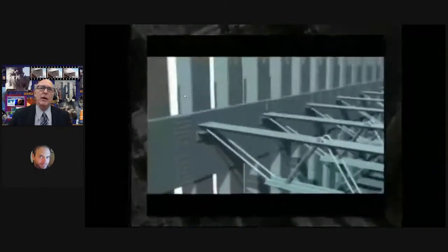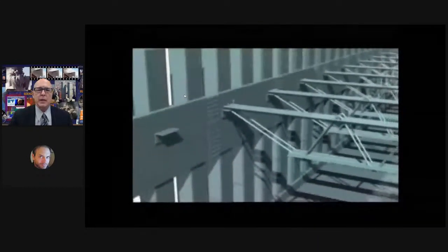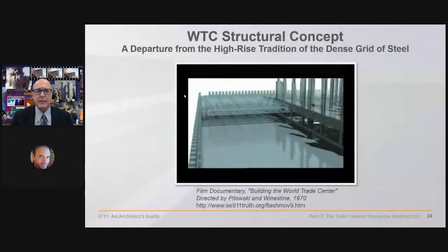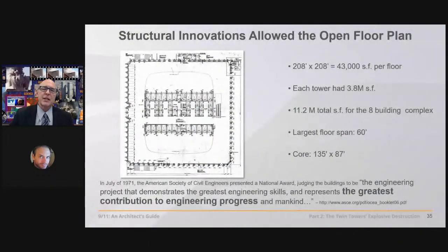Between these two structures was laid the horizontal diaphragm, or the floor system, with concrete poured over lightweight steel trusses. So this is where NIST focuses its investigation, as we'll see, on the vulnerability of these lightweight steel trusses. But design-wise, what that allowed is 60 feet of open office planning on this side of the hoistways, and then 35 feet on the sides.